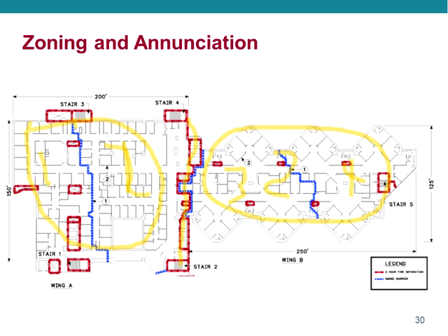And if you're doing a high-rise building or a hospital or a large footprint building, there will be in most cases an emergency communication system, and you will be zoning that appropriately according to the fire separations of the building. Because in many cases it's not practical to evacuate the entire building at once, so we have to evacuate partial parts of the building or relocate.